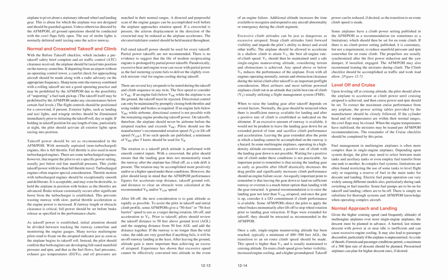If an excessive amount of runway is available, it would not be prudent to leave the landing gear down for an extended period of time and sacrifice climb performance and acceleration. Leaving the gear extended after the point at which a landing cannot be accomplished on the runway is a hazard. In some multi-engine airplanes, operating in a high-density altitude environment, a positive rate of climb with the landing gear down is not possible. Waiting for a positive rate of climb under these conditions is not practicable.